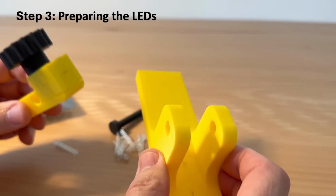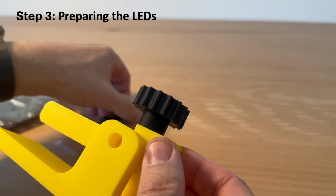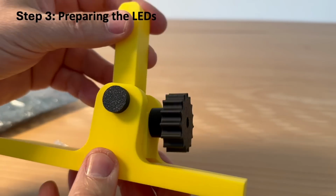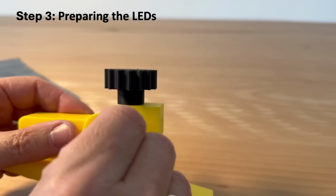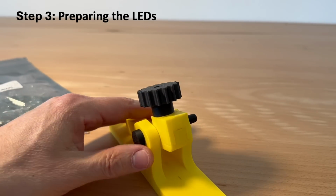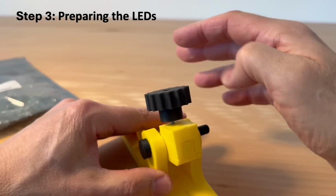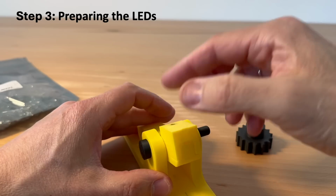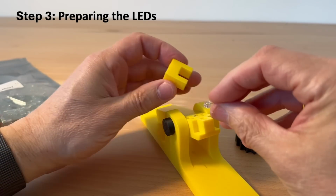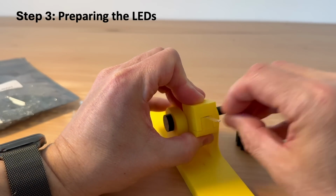To solder the LEDs properly onto the PCB, the connection wires need to be bent at a 90-degree angle in the correct position. To make this bending process both precise and easy, I designed a custom bending tool and 3D printed it. The LED is placed into a slot in the tool and a lever is used to bend the wires exactly at the right point. Let's have a look how that works.